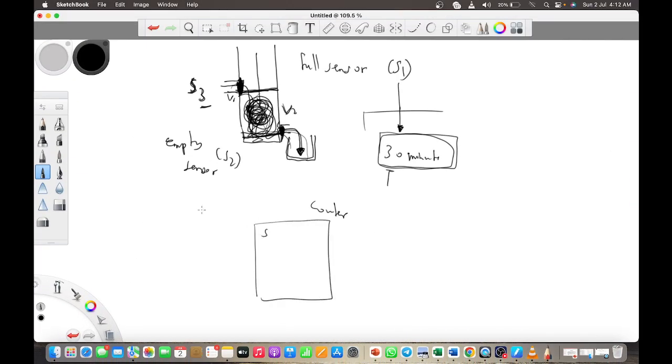So, when it comes on, there are 2 conditions. Either of them. Either when I press I0.3, the valve will open and the process will start. Now when the process ends, the valve will open again because it must run 4 times. So that condition is here.